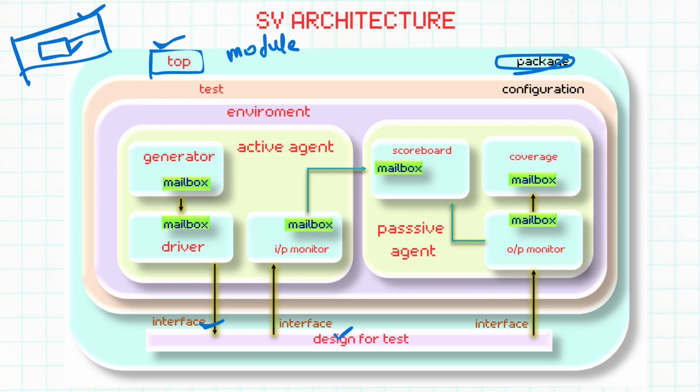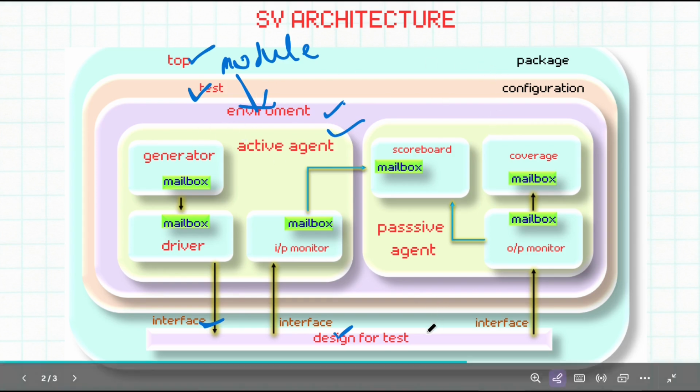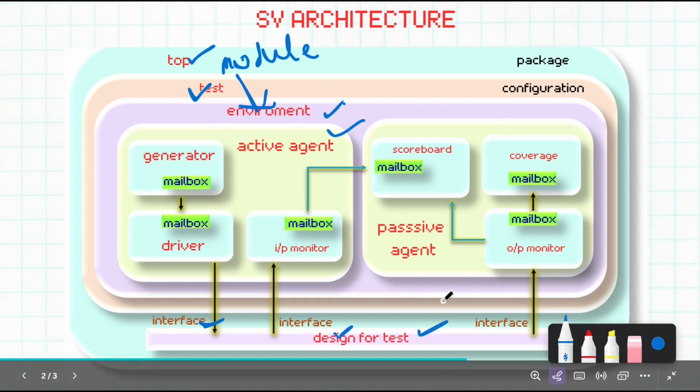Now after deciding the test cases, in the second step we will write the test cases in our test bench. Now our test bench is created and our components are working. First we will run a sanity test case, and then we will write our scenarios for the features inside our specification. Up till now we don't know what is inside the chip or what the components inside the chip are. We are just taking our specification, writing our features and scenarios, and verifying our test case and our expected output, which we will discuss with our design engineer.